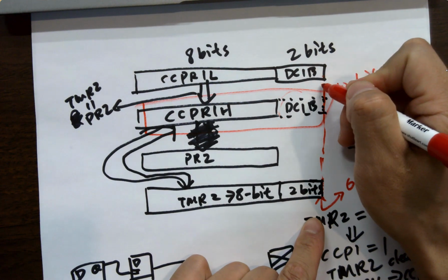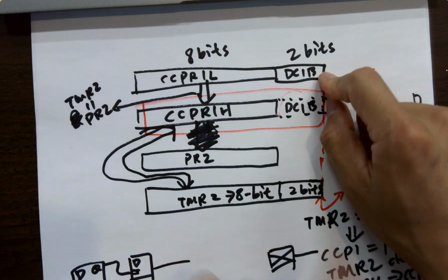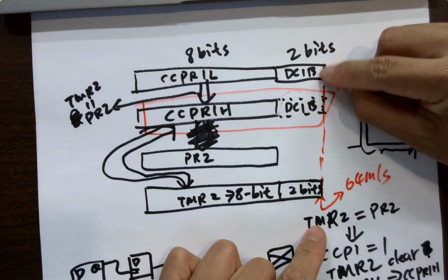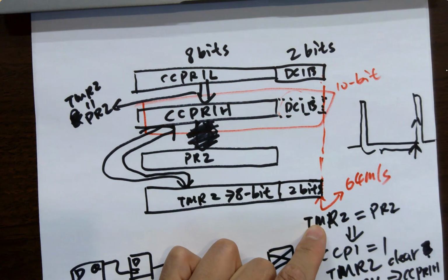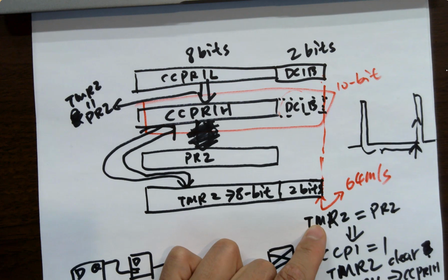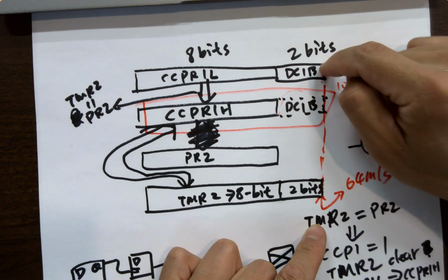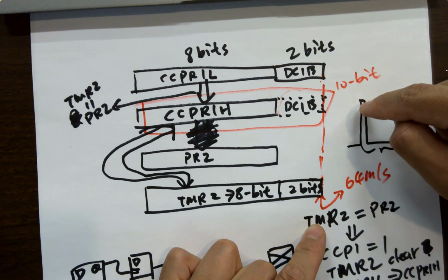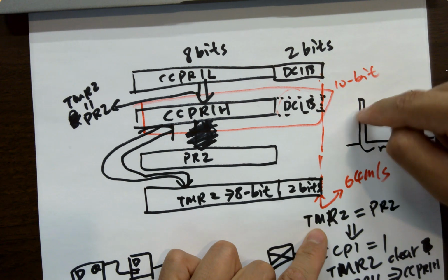And this is aligned with this one. Am I toggling this LSB? Same question, same silly question. How can you toggle a register? It's just a constant. You write into it, okay? It stores the value that will give you that duty cycle. What you are toggling is a counter.